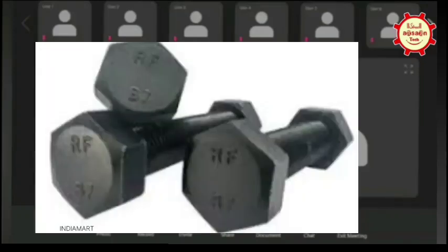Let's just say, for a ballpark figure, for SA193 the limitation is for 50 mm diameter, and our diameter was 60 mm. So the AI was asking how you are going to justify whether this meets the requirement of the code in this statement. Ramakrishna or Abhishek, did you get the query? Now, what is the requirement as per code for the bolt diameter?